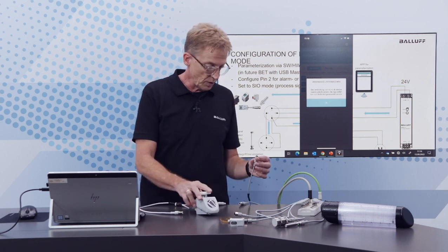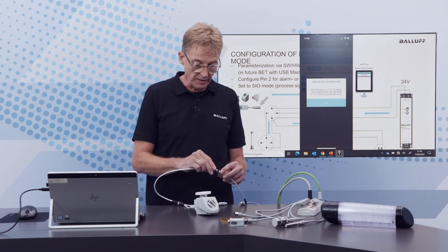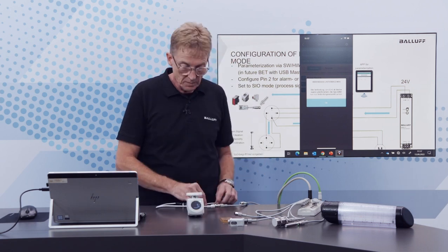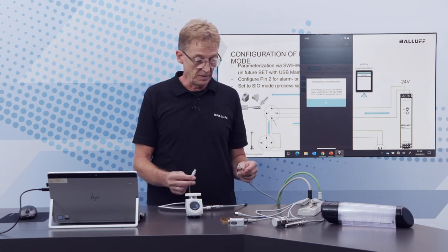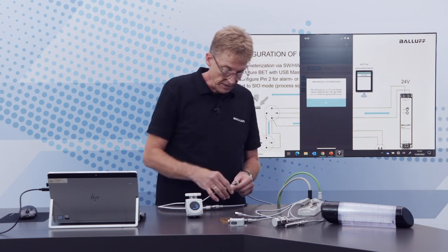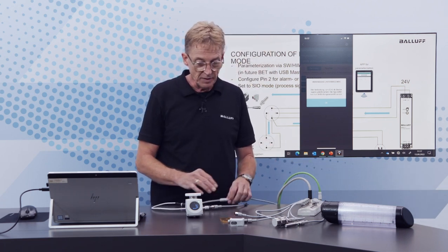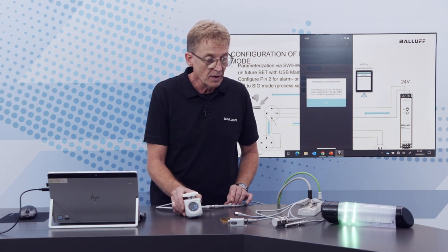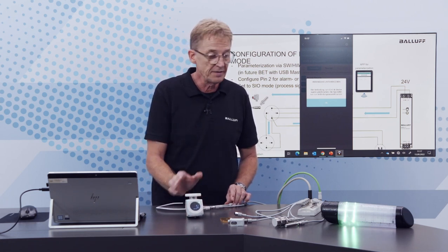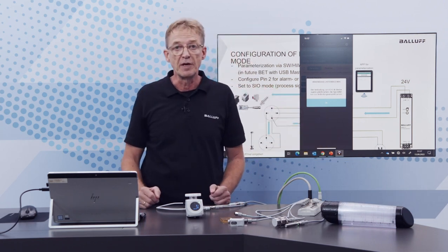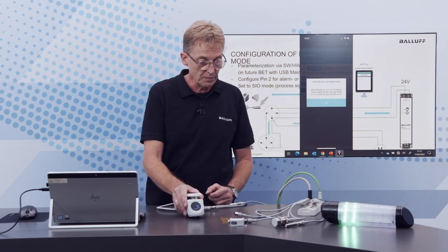And we're just working with a 24-volt power supply here to run the BDG, and we connect the standard signal light here directly to pin number 2. And that means whenever there is a vibration here on this device, then I will have this information directly on this port.